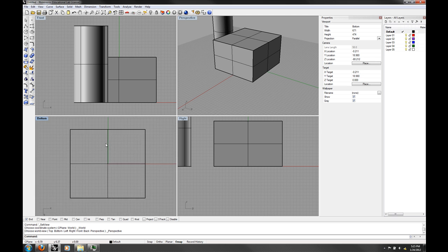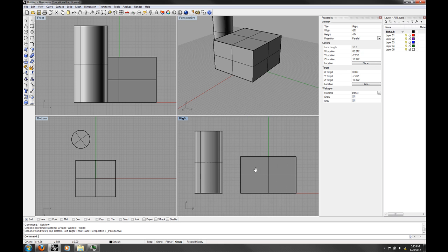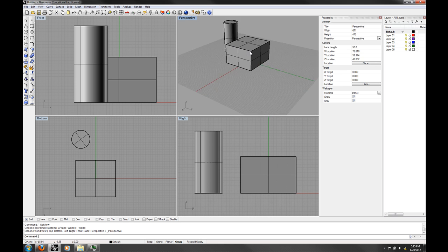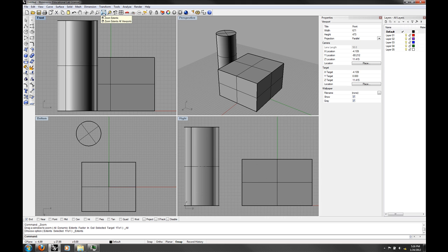Use the scroll wheel on your mouse to zoom in and out. That should be pretty familiar. So you can go in and adjust the zoom of these things. You can also use zoom extents. Left click zooms the window so you can see all the objects. Right click zooms all the viewports to the extents. So again, that's an interesting little tooltip that pops up, right? The left mouse button is zoom extents, right mouse button is zoom extents all. So that's something that's pretty useful.